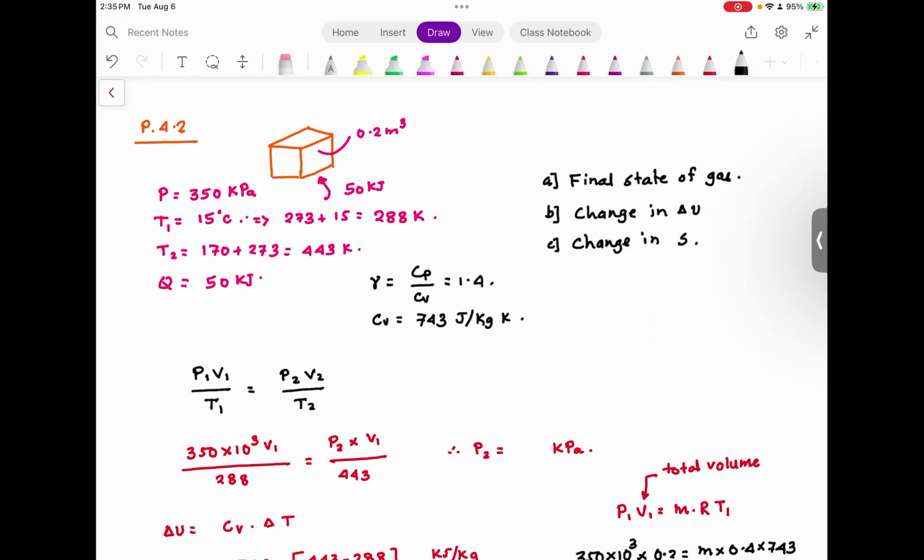Flow work from the gas law, PV is equal to RT, because m is considered to be 1, because v is the specific volume. So it's the volume per unit mass. Put this in this equation, and you get this fundamental equation. The difference between the specific heats is nothing but the value of the gas constant. Are you with me?